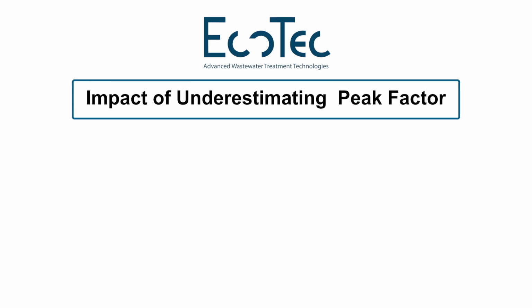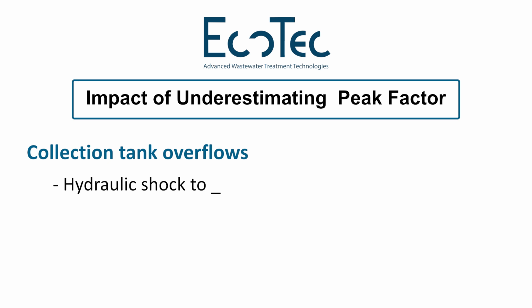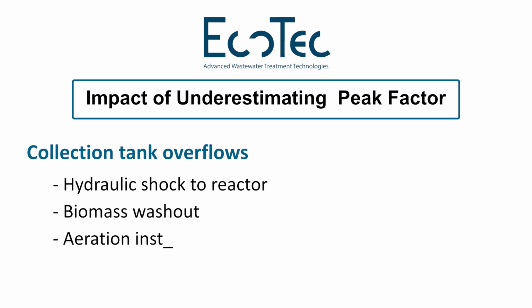If this is not considered, what can happen? The collection tank may overflow. There could be a shock in the reactor because the usage pattern is different, and the values of BOD, COD in the water may be high during certain times of the day, and the aeration is not so stable because the influent water is not coming as more or less equalized flow. Of course, finally, the quality of treated water suffers, and maybe the plant doesn't even give consistent results any time in a day.